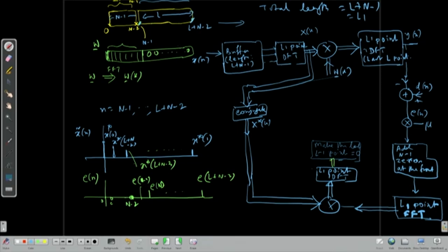So, here what I get in the time domain is the new weight, but I am working here in the frequency domain. So, now there is an updated weight, where I have got the weight values here, and as before zeros here. So, on this extended updated weight block, again I apply FFT, because I have to go to the frequency domain WK. So, I apply FFT.